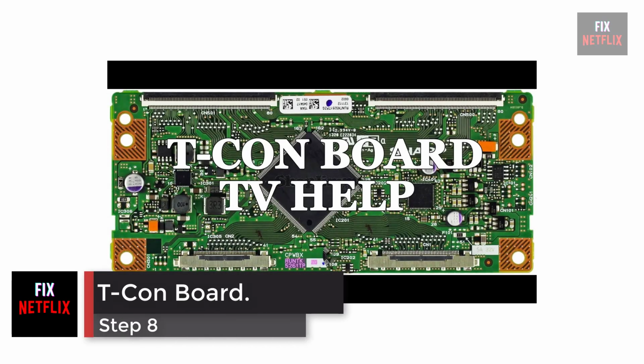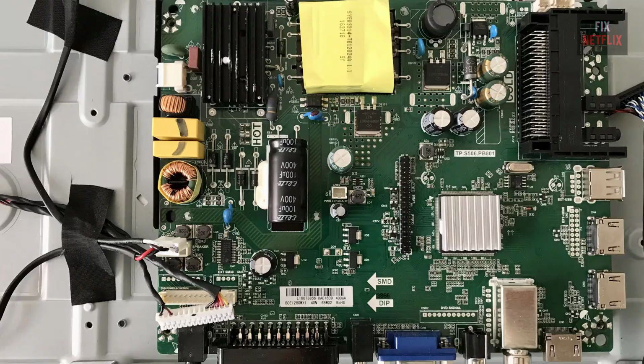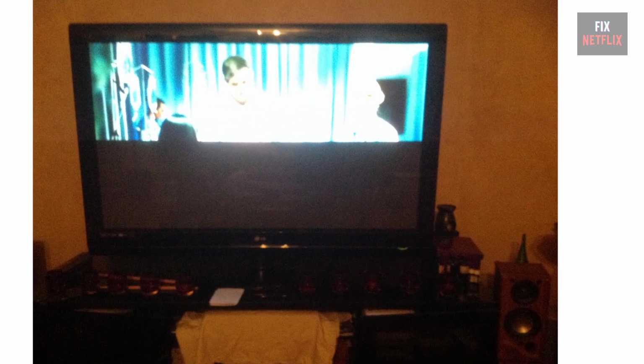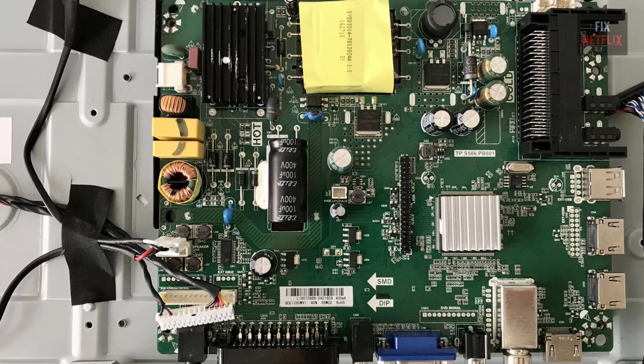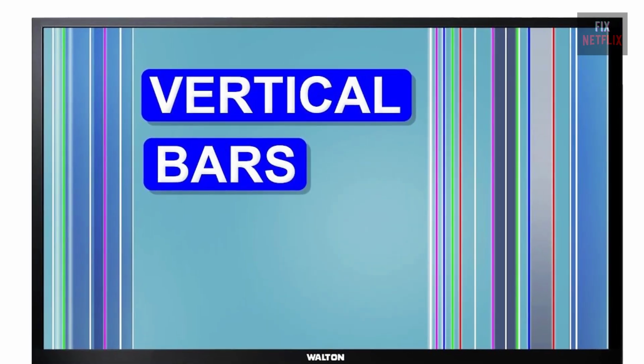Step 8. T-con board. This check for the T-con board also touches on the condition of the main board. Note that problems that show up on half of the screen, like bars or such, point to a failed main board, as T-con board errors show up on the whole screen. As an example, if an error like bars on the screen is on the whole screen, it is likely the T-con board.